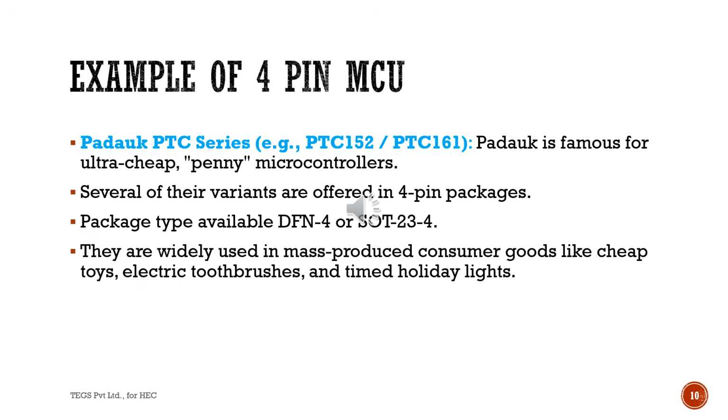Example of 4-pin microcontroller: PTC series, PTC152, PTC161, Padauk, is famous for ultra-cheap penny microcontrollers. Several of their variants are offered in 4-pin packages. Package types available: DFN4 or SOT23-4. They are widely used in mass-produced consumer goods like cheap toys, electronic toothbrushes, and timed holiday lights.